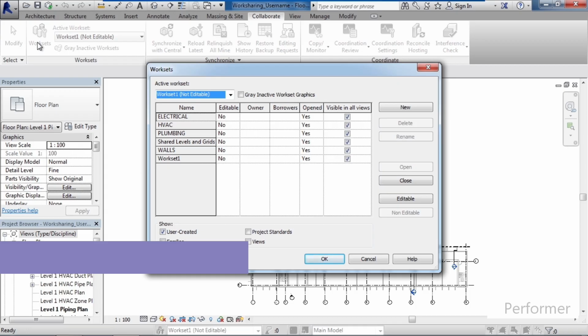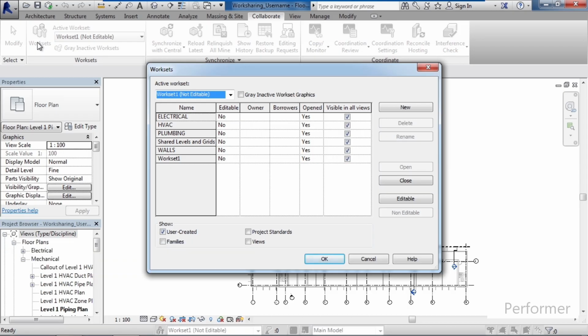However, it could be detrimental too because if you're working in a team and someone else is using a shared workset, you can't necessarily modify it because you have it locked. Now, another reason to actually take ownership is if you're under design review. So if something is designed and you do not want to allow anyone to make a modification, whether purposely or accidentally, you can take ownership of the workset, therefore locking it.